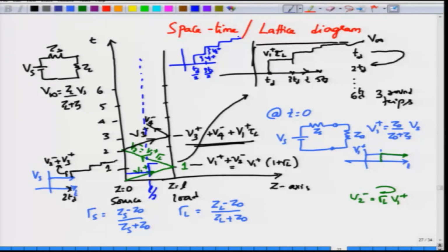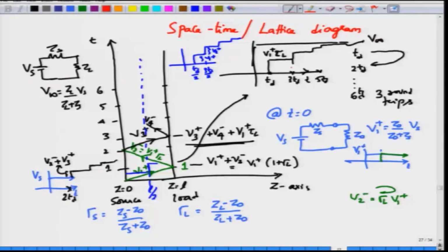Okay. Again I am showing all of them to be increasing, but in the next module we will actually put down the numbers and then consider some very special cases which are also very important to see the effect of different types of loads, or rather different values of loads, and how they would affect the signal integrity. To give you a basic idea before we go, the idea here is that if I have a logic gate and another logic gate connected by a transmission line, and if I say that I need a certain voltage at the load IC for it to be considered a digital 0 or a digital 1. So, let us say digital 1. So, a digital 1 requires a certain threshold voltage V.